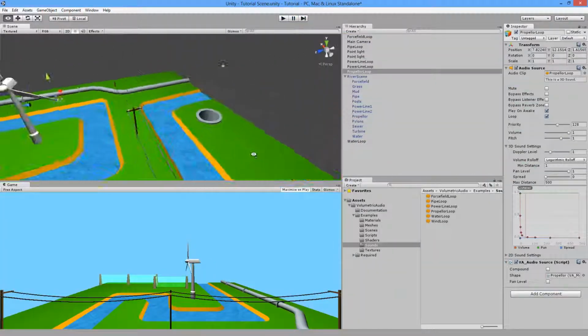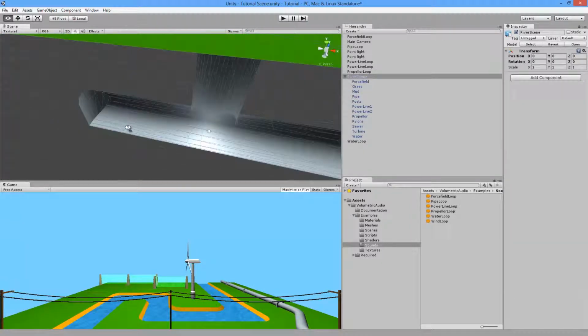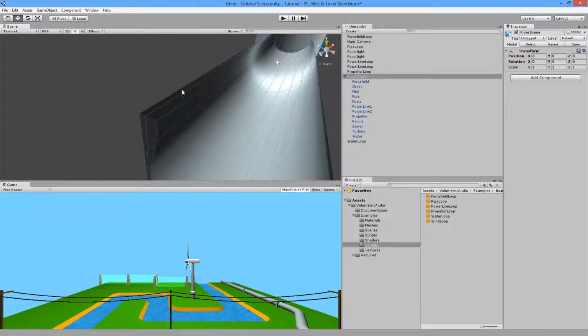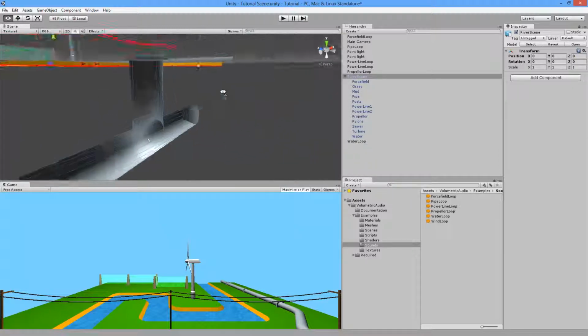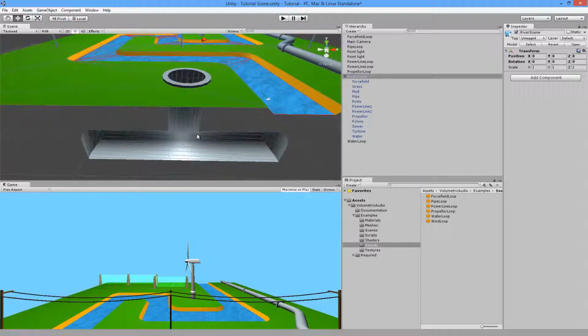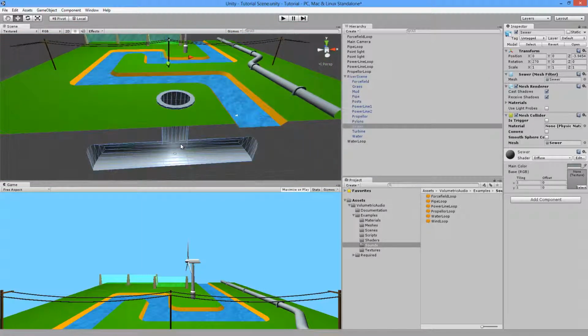So finally I'm going to show you a compound object. Here we have a tunnel that has holes in it. As you can see, we can see the back faces of the triangles, which is an easy way to tell if there's holes in the meshes or not. So because we can see the back faces, that means we can't uncheck the is hollow value for this mesh.